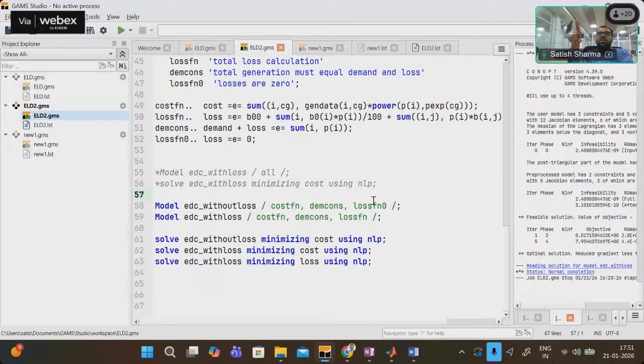In an actual system, it can never happen that the demand is 350 and only 2 units are available which can only supply 300, because there will always be an estimate that there will be a certain demand of 350, and for that demand the system operator will keep at least 3 or 4 units committed well before.